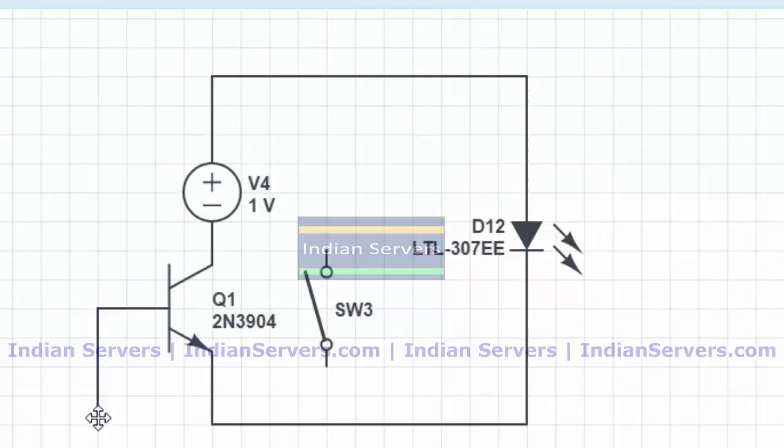If I connect this base signal to the controller, easily the controller or processor can turn on the light automatically with some delay, or according to the application. Like that, manual effort can be avoided or removed by using transistors. So from this scenario we can conclude that a transistor is acting as a simple switch. Whenever we supply a base signal, current will start to flow from emitter to collector, or otherwise it will remain an open circuit.